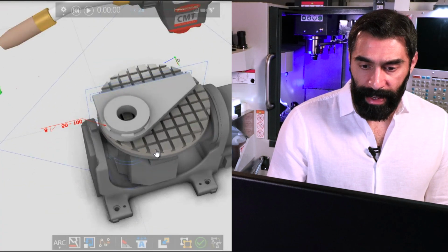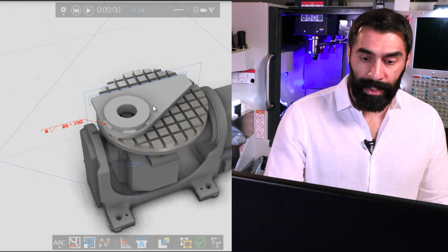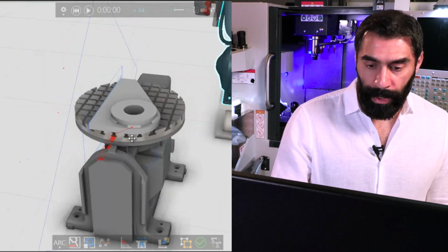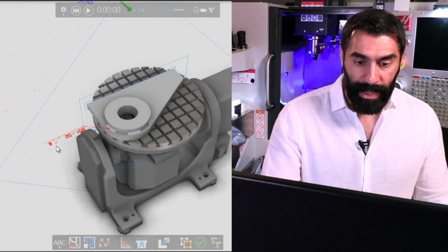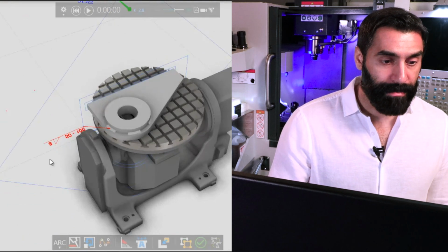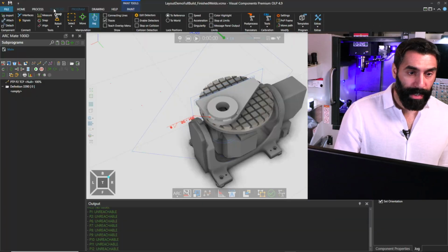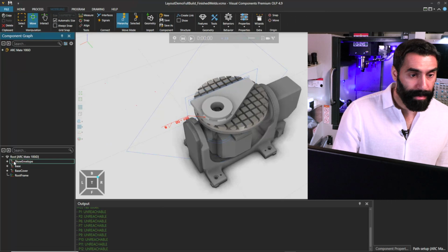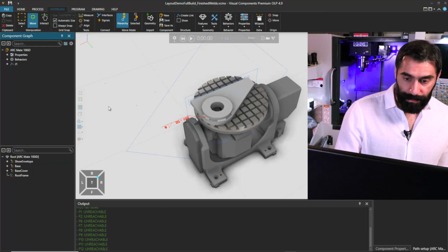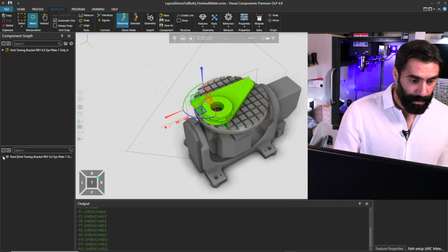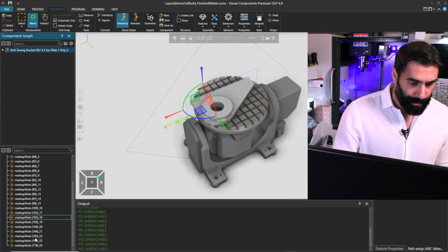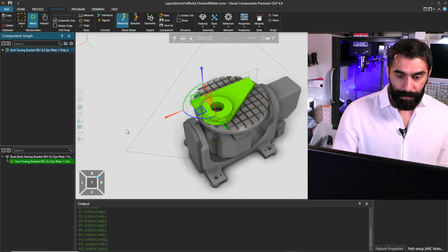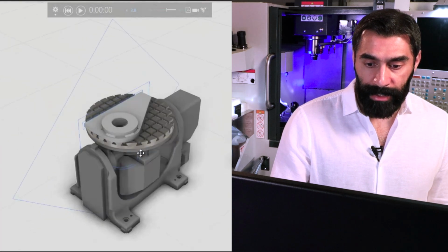With that, you can see that as we imported the step file, in this case we saved it out as a step 242, so you do see the weld callout associated with the weld. We don't need that in this particular case because we will be importing the QIF definition. So we can go over to the modeling tab. This is not necessary, but we can delete the markup for clarity. Now we just have the CAD geometry.